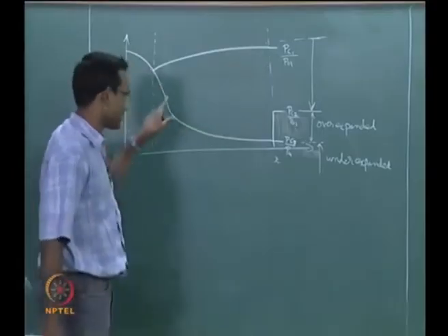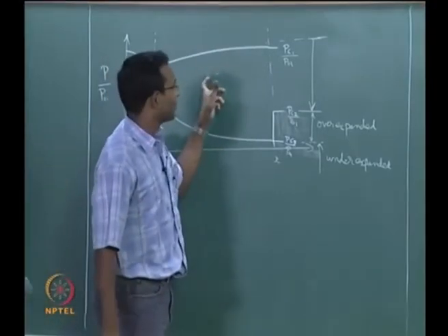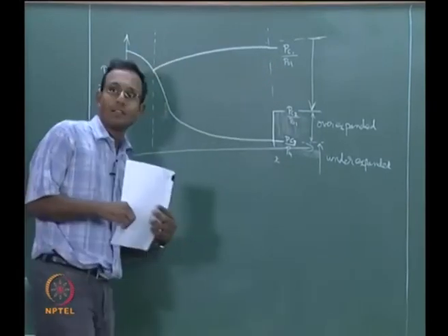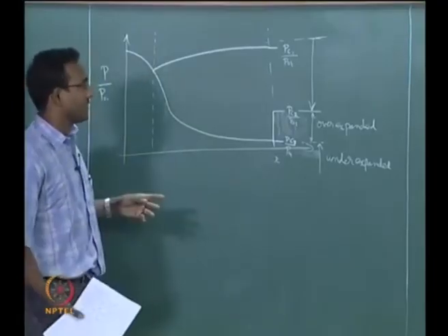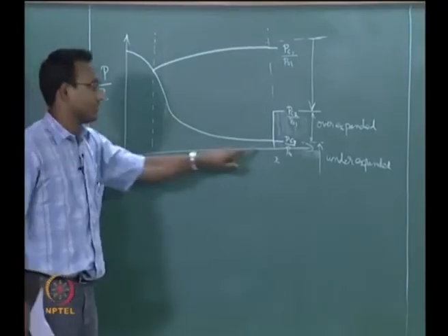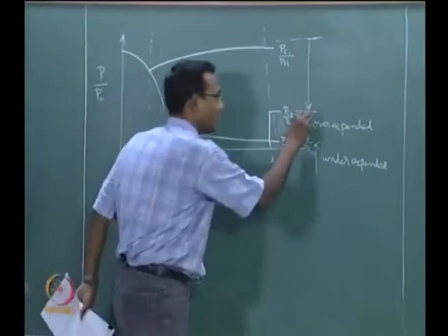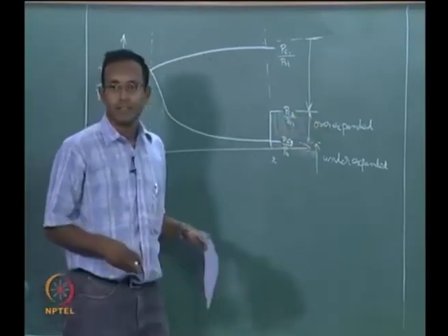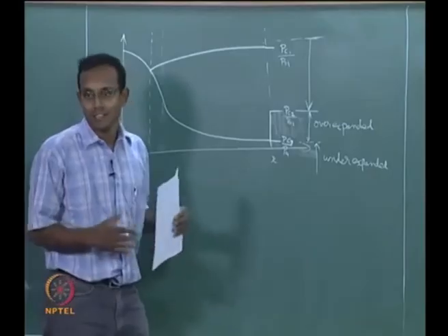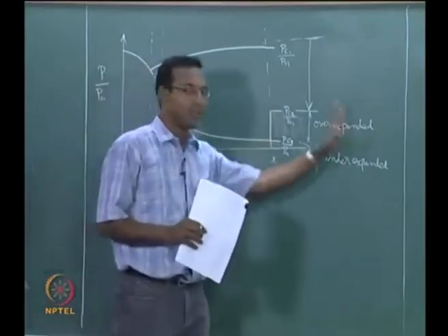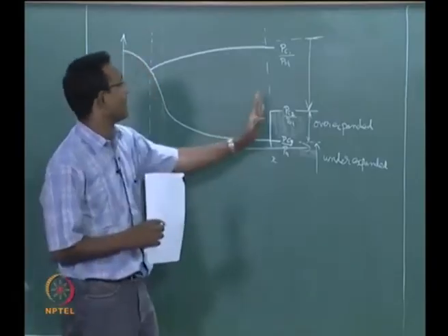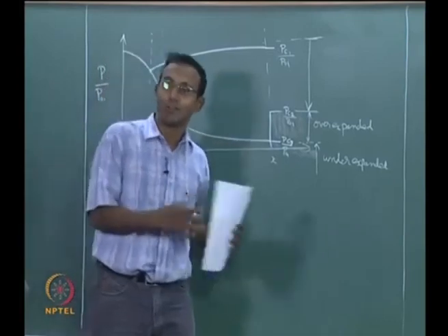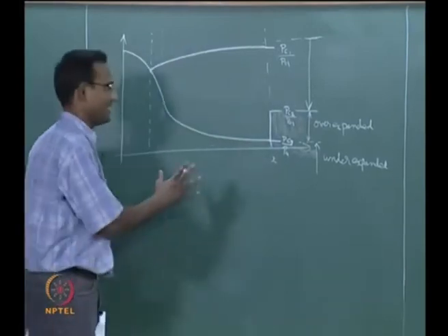After that there will be a shock inside, and after that it will become subsonic and it will rise up to that pressure, and there will be a point where the shock comes to the exit. After that we said there is no change inside the nozzle. Now we are outside, we want to solve for this region, this extra region here, over expanded cases. I already told you the change is only outside, so we are going to talk about the jet coming out from the nozzle. From now on we won't consider whatever is happening inside, it is all done, all old history for us, we know how to solve it, we have already solved one example numerical problem also, we will say that is easy to solve.